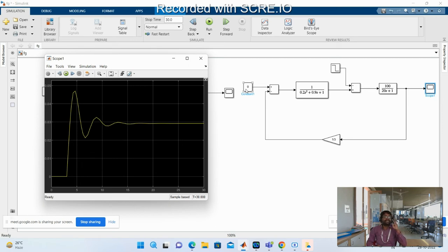So that is case 3. For that we are using the PI controller. What will the PI controller do? The PI controller will sense the frequency deviation and feed the signal to your speed changer, and the speed changer will change accordingly based on your frequency deviation, and it opens or closes the steam valve, and finally your system will regain its normal frequency. Do you agree? I think so.